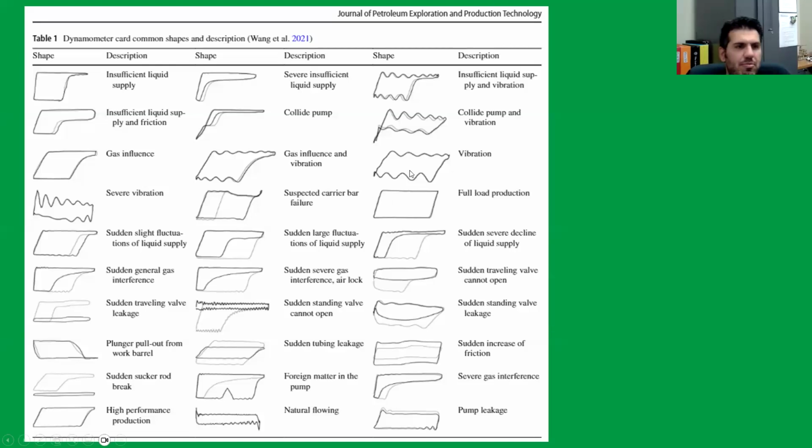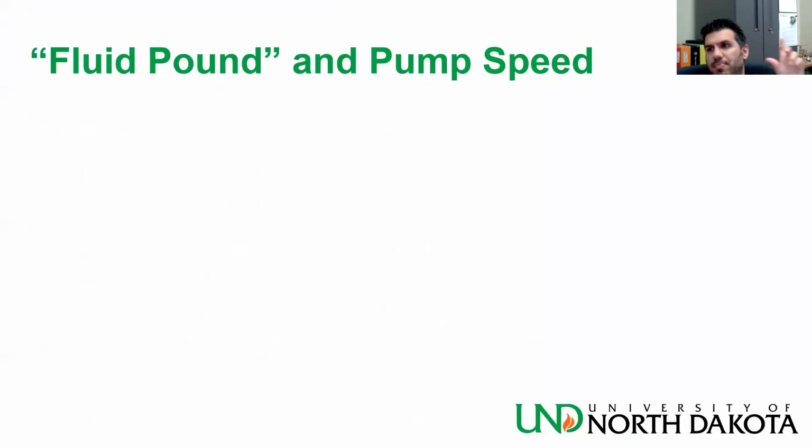A common problem that comes with depletion, though, is what we call fluid pound. That is, the pump is not getting filled entirely with fluid. And in this case, this is bad. It means I'm under operating my artificial lift system. I don't let the barrel downhole fill up.